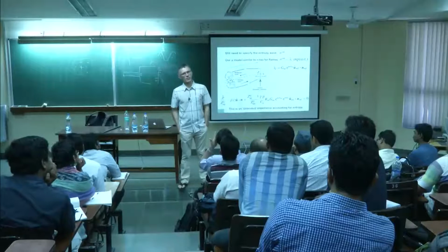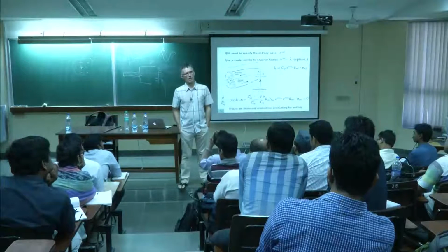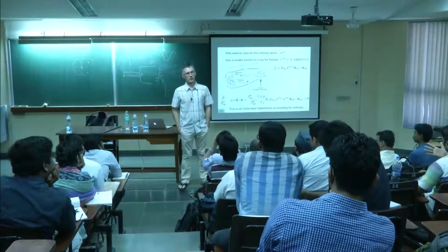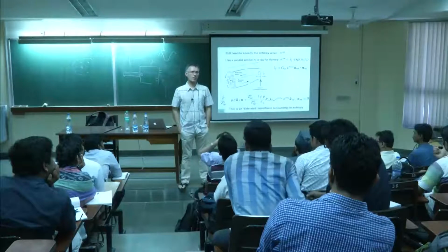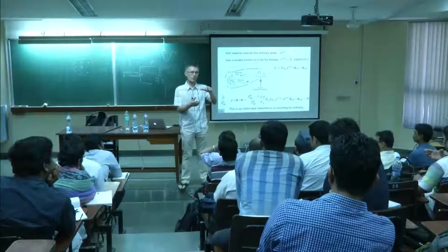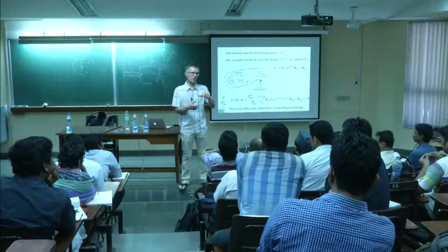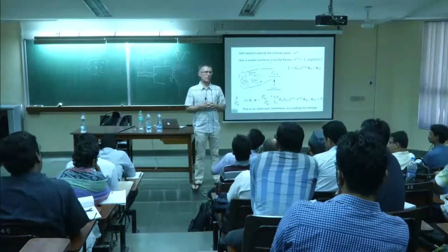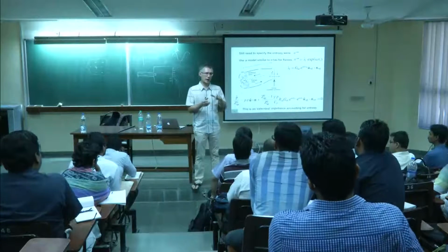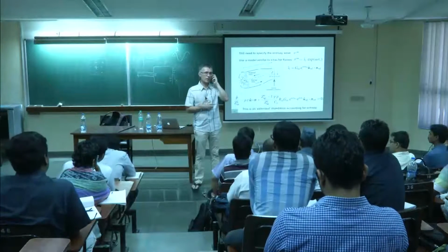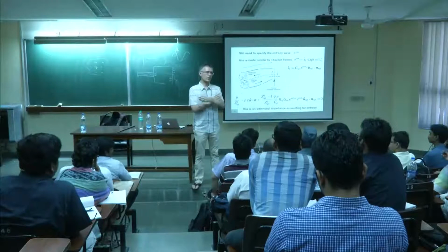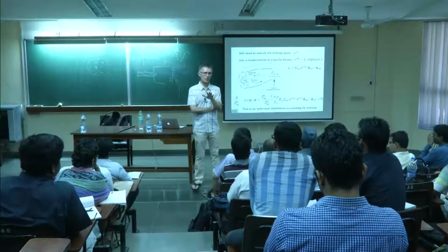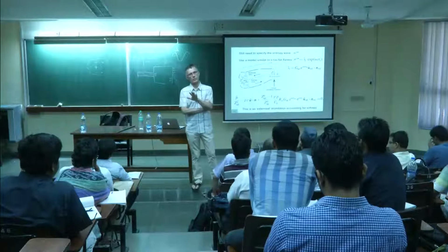Well, they don't call it azimuthal, they call them transverse. DLR has quite a few experiments on that. I suspect Purdue too, but they don't have a lot of diagnostics, you know. They have maybe 2 or 3 microphones. So it's difficult to say if the mode is azimuthal, transverse, or longitudinal, because the mode is so complicated that to identify the mode, you would need a lot of sensors. I think it's the problem of DLR at the moment. This is why they're working with us. They have a limited number of sensors, and from a limited number of sensors, being able to find the mode is difficult.